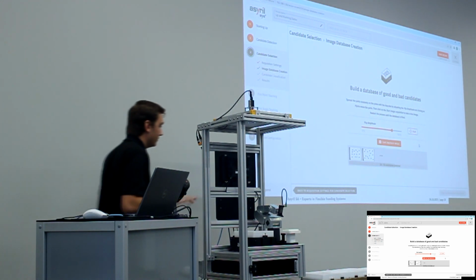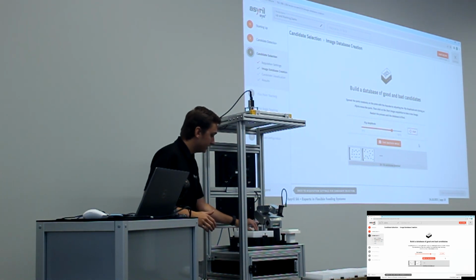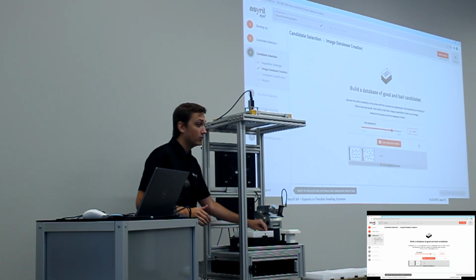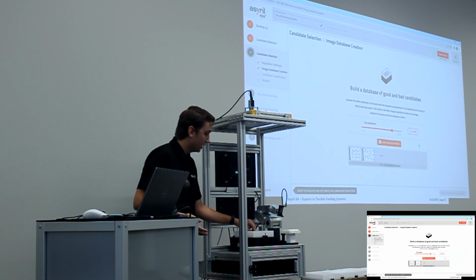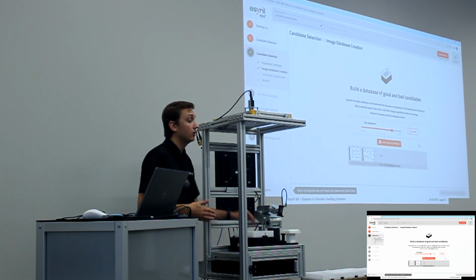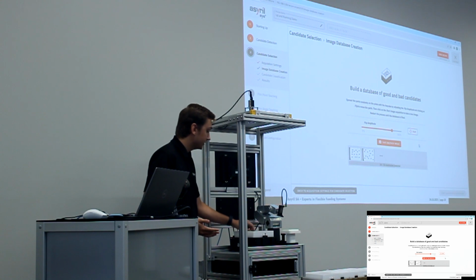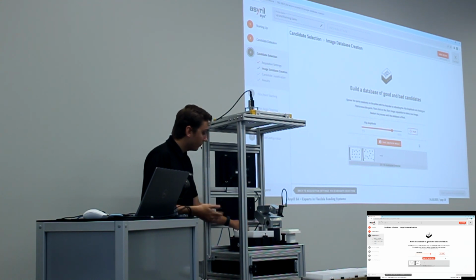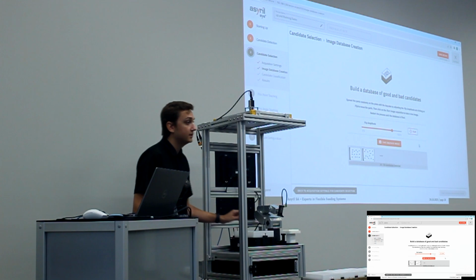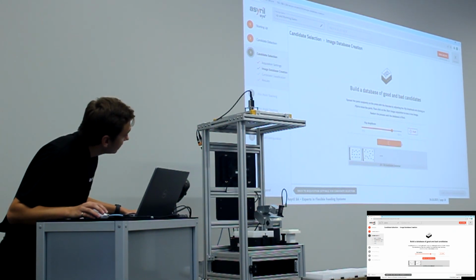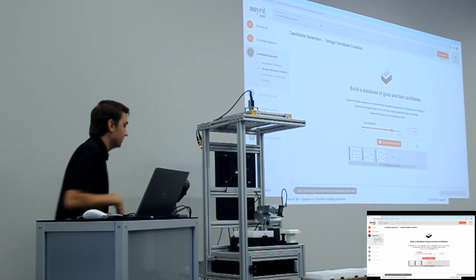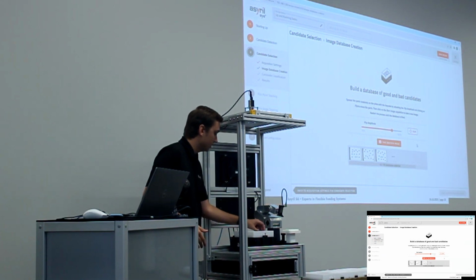And then I'll flip them over into the bad orientation. Because we filtered out by size two of the orientations already, like on its side or vertical, we don't need to account for those in here because they're already removed from the last step. If they weren't filtered out by size, you would also need to account for those bad parts. So try and make sure that you cover all of your incorrect orientations in this as well, so that the AI can properly detect bad parts.